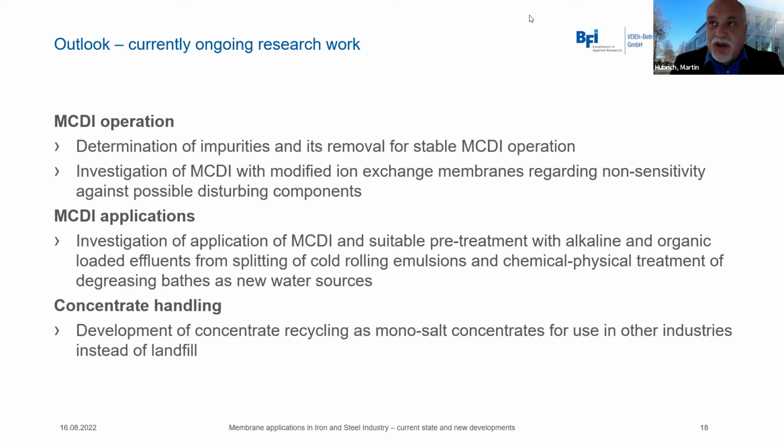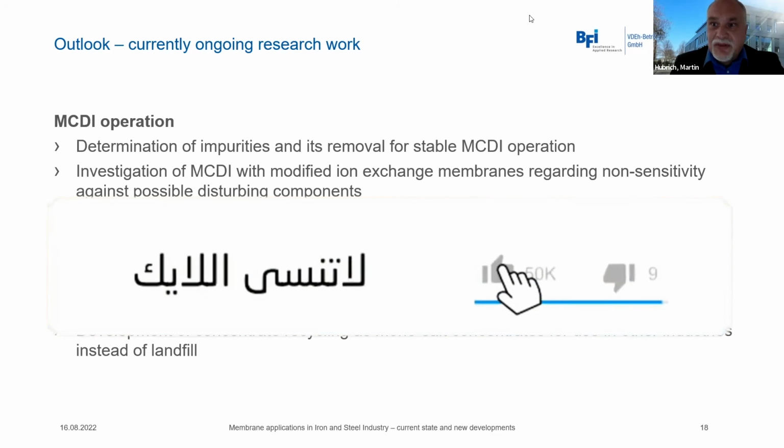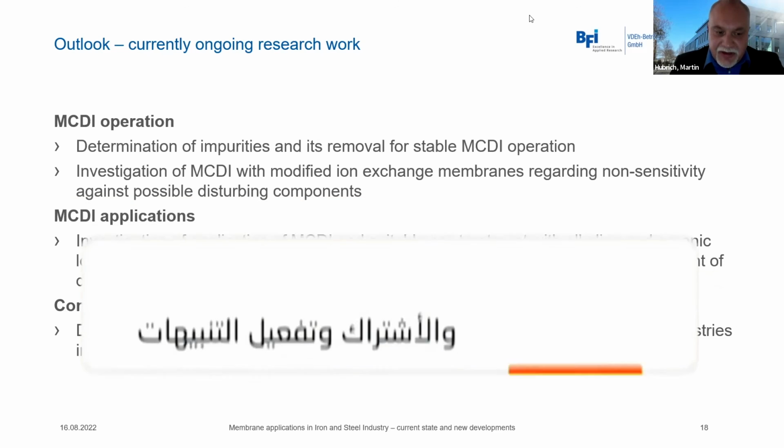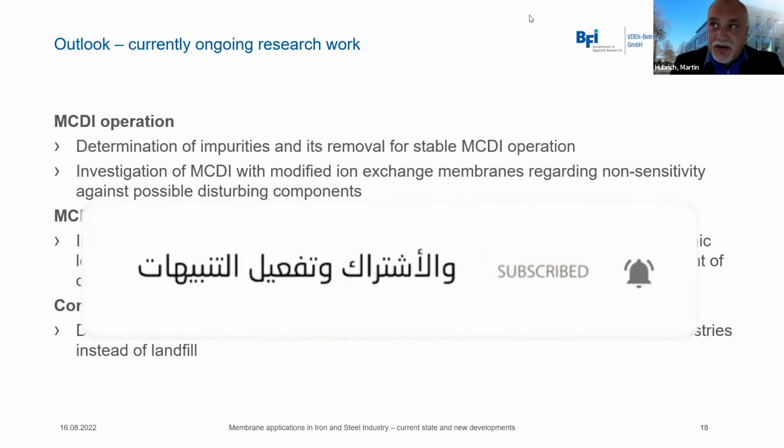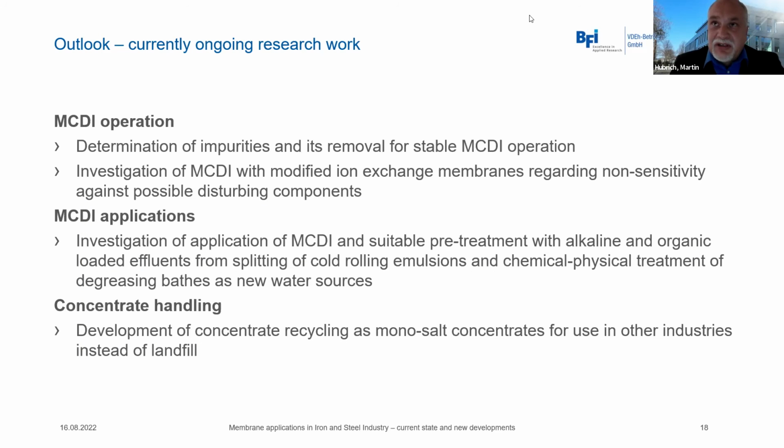By the time you have to clean the MCDI modules, you can do it in an automatic way, just using compressed air, or you have the other option that you can use acid, if it is possible. It depends on your application, and the hardness content. Regarding biofouling, we did not see any effect in all the applications we have been investigating.